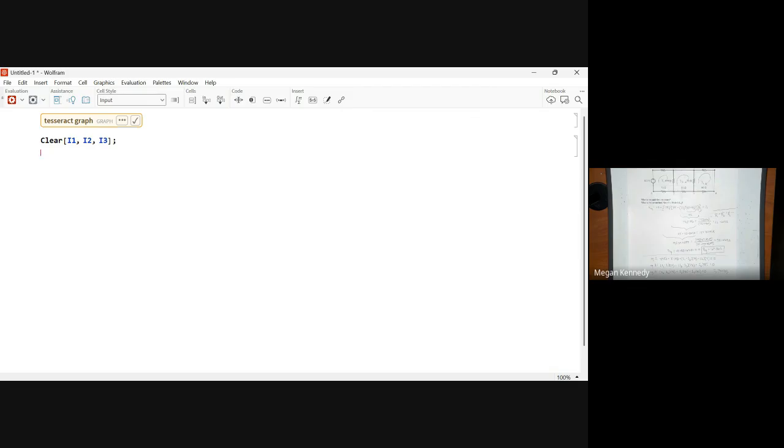Now, when you're doing it, depending on your problem, you might be able to set up different variables in here, which is definitely helpful when you start getting to AC systems. You can set up your voltage sources, your current sources, you can set that all up beforehand. In this case, since it's fairly simple, I'm just going to start writing the equations. So I'm going to write in our equation 1, and that is equal for negative 3.2 plus I1 times 43.